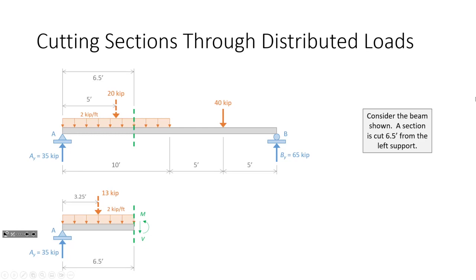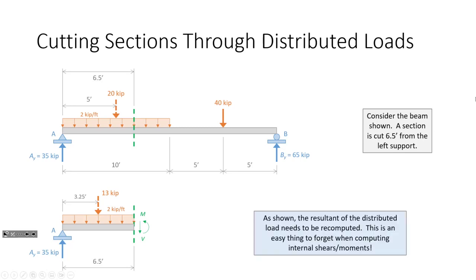Okay? I can't tell you how many times I've seen students put 20 kips down here. No, don't do that. That is not good. I've seen that happen all the time. The distributed load needs to be reassessed. That concentrated effect needs to be recomputed.